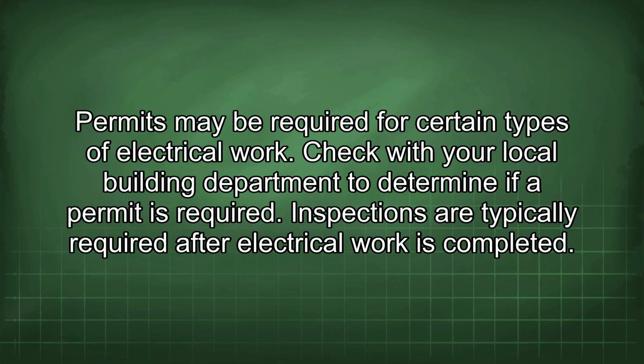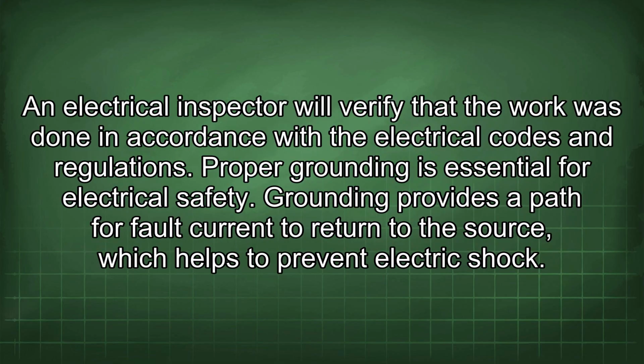Permits may be required for certain types of electrical work. Check with your local building department to determine if a permit is required. Inspections are typically required after electrical work is completed. An electrical inspector will verify that the work was done in accordance with the electrical codes and regulations.